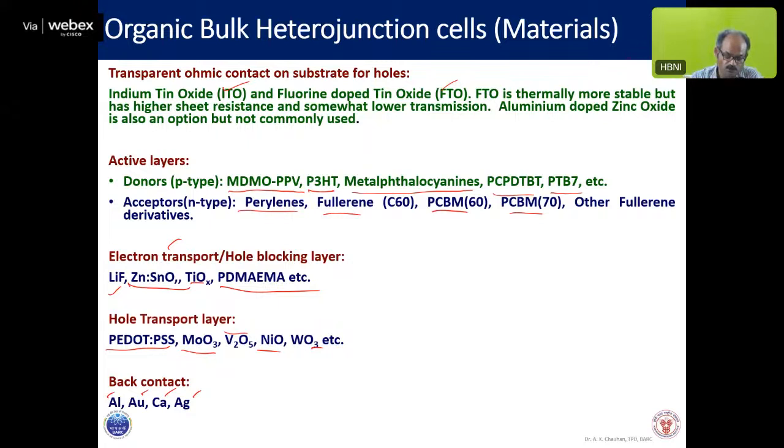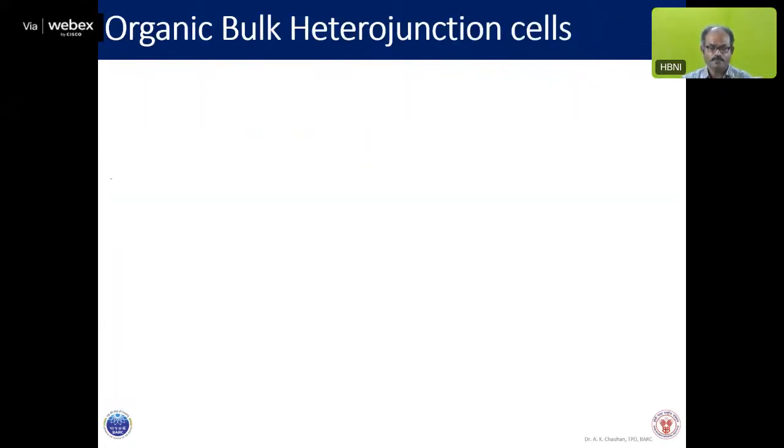However, when you want to select such materials, you need to take care of the work function of this material and the HOMO-LUMO levels of your donor and acceptors. On the basis of that only, you will be able to decide a correct back contact material.